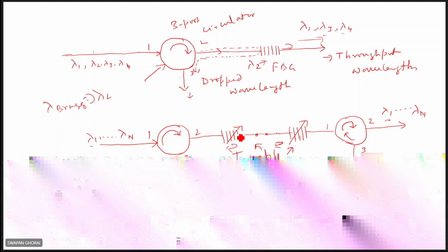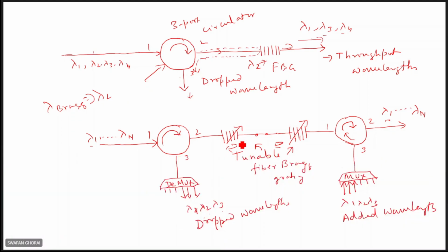And these gratings are tunable. You can tune the fiber Bragg grating wavelengths to a particular wavelength. I mean, lambda Bragg, as I mentioned just now, is twice the effective index times capital lambda, right? So tunable means that by changing this capital lambda, the periodicity, you can change the lambda Bragg. That's why it is called tunable. By using temperature or strain, you can change the periodicity. So I can change the parameters. Right. And you see it here.